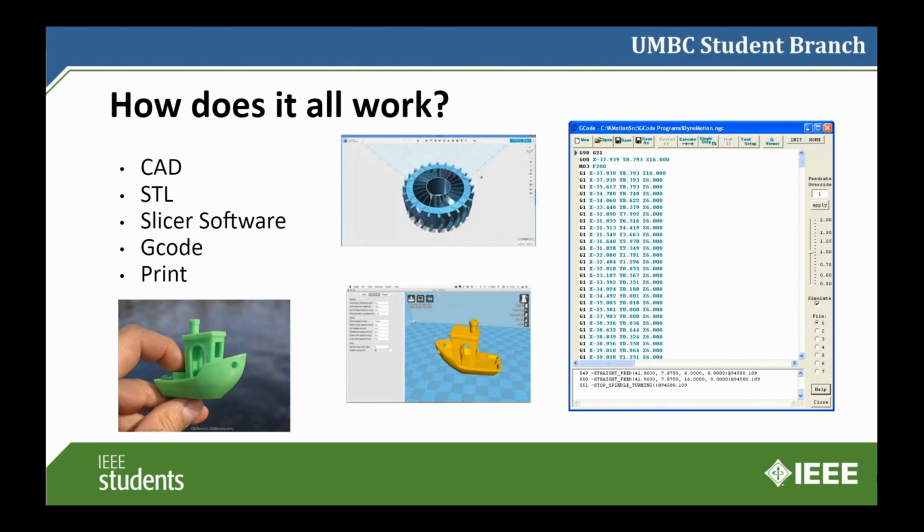After that, depending upon the different settings in the software, you can change the settings for your physical 3D printer. As you're slicing or figuring out exactly where you want the 3D print to physically be on your base, you can change the temperature of the extruder and the layer height. You can change a lot of other things like retraction.